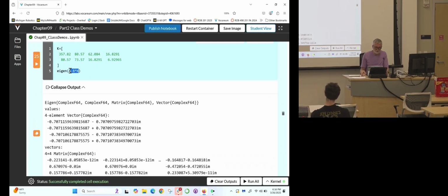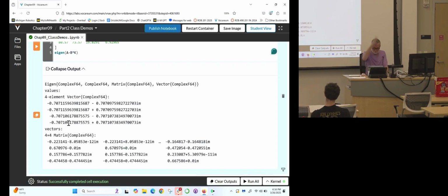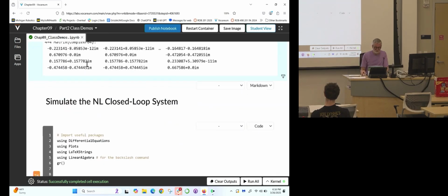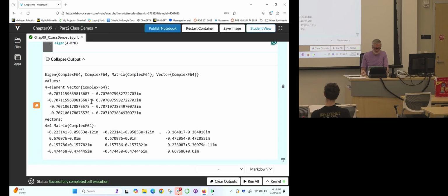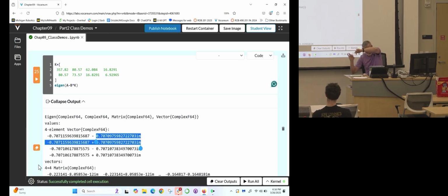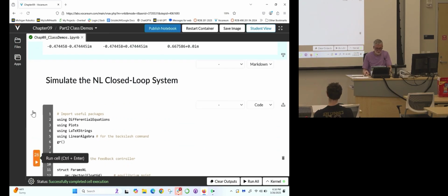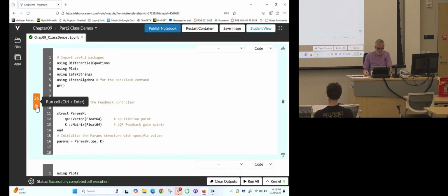This gain is modifying the eigenvalues of this two-link pendulum. Notice what they are now. Real parts negative. Real parts negative. Yeah, we've got imaginary parts, but the real parts are all negative. This is what feedback is. It takes eigenvalues that are not negative, they're unstable, and it makes them stable. And I simulate the nonlinear system.